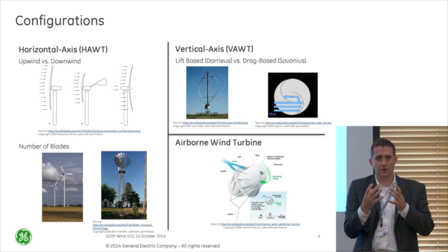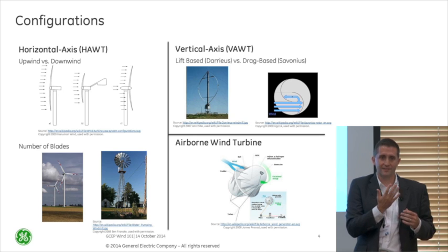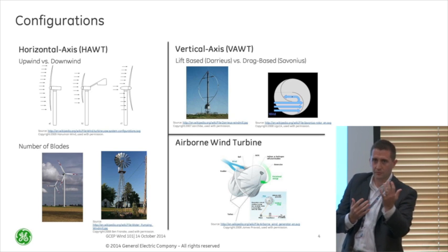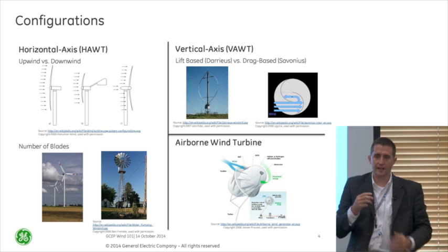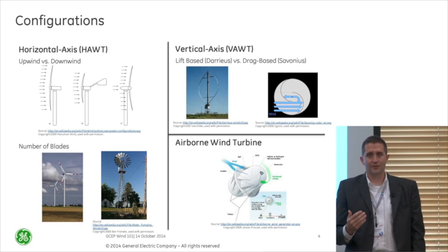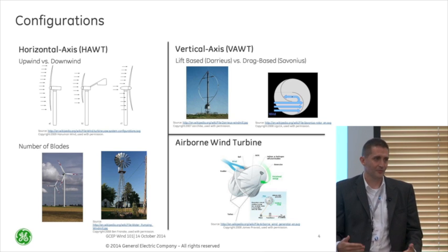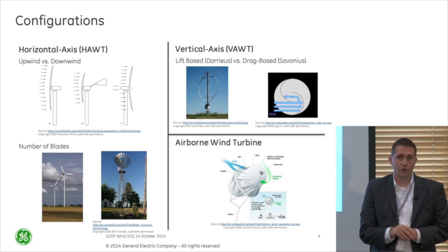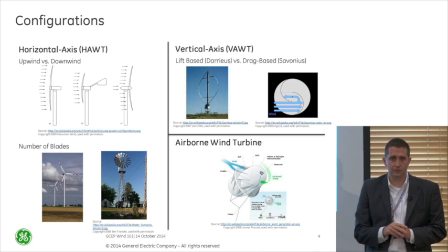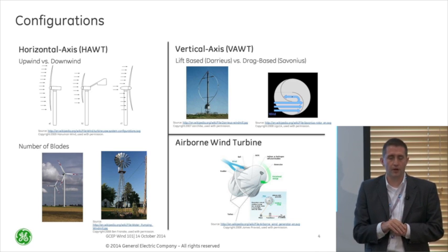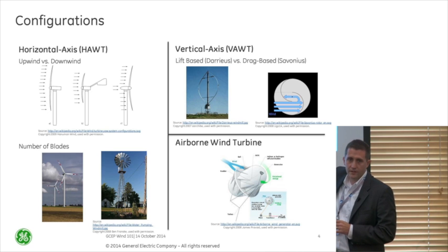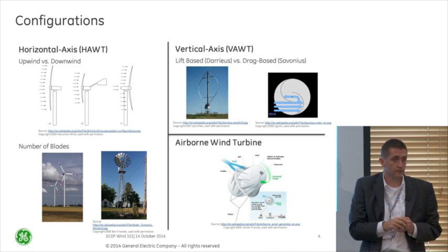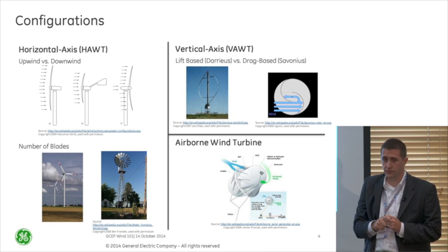The wind gets really low because it has this big wake effect. And now every time that blade passes, it has a big wind, no wind. And it goes back around, big wind, no wind. And it has really high fatigue loading. And when you're designing something with that big of a fatigue loading, let alone often an audible noise that happens every time you pass one of those blades through, it becomes a bigger problem. So you don't see those quite as often that way. So the industry is mostly this upwind type with the active yaw.